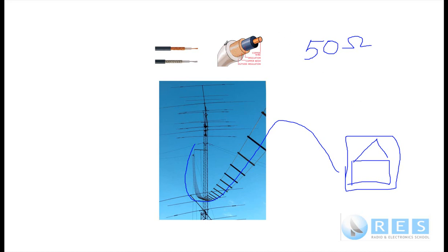So we make radio transmission lines 50 ohm impedance. We can make other impedances other than 50 ohms, but 50 ohms is the best impedance for low loss and power handling of radio transmitters. That's why we have 50 ohm line, and the manufacturers of transmitting equipment make the power amplifier of the transmitter 50 ohms so that we can get maximum power into that line. A little bit more about that later on.